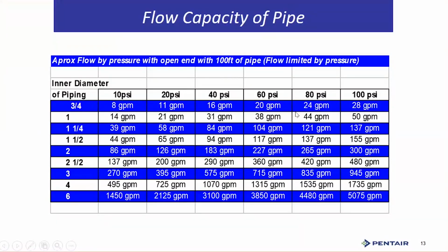And that was probably on a 2-inch valve. That valve is probably able to handle something in this range of flow down in here. So understanding your flow demands is critical to getting this right in sizing the valve.